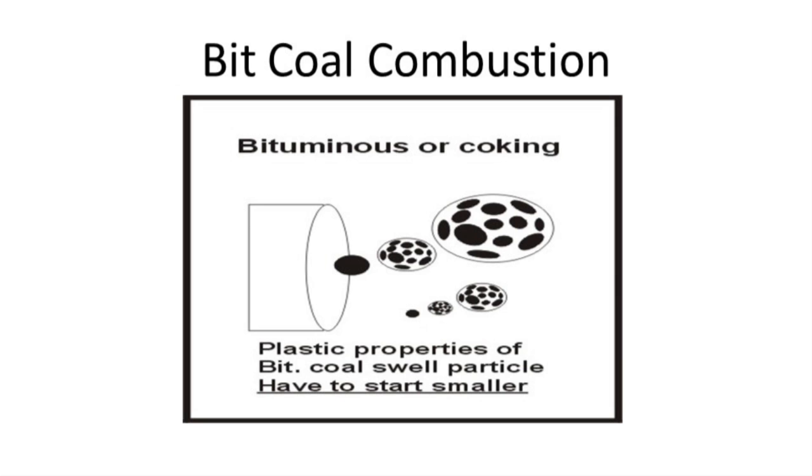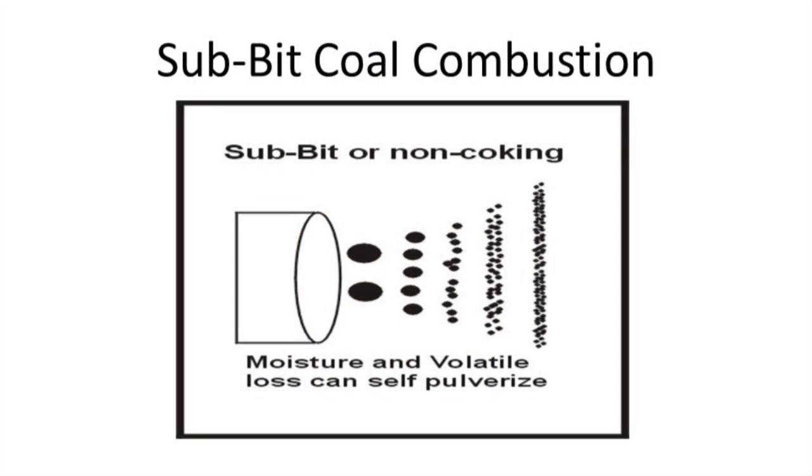So with bituminous coal people, we can have the problem, but I mostly see the problem with particle sizing coming from the subbituminous coal users. The subbituminous coal users need more throughput of tons through the mill, so not grinding as fine actually adds capacity to the mill. If you look at the carbon in the ash or the LOI from a subbituminous coal, it could be very low even if the sizing is not quite right.